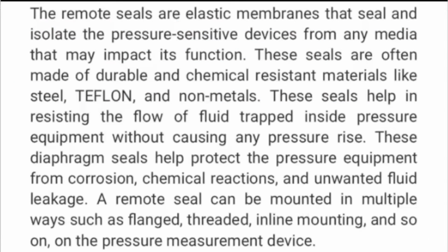Remote seals are elastic membranes that seal and isolate the pressure sensitive devices from any media that may impact their function. These seals are often made of durable and chemical resistant materials like steel, Teflon, and non-metals. These seals help in resisting the flow of fluid trapped inside pressure equipment without causing any pressure rise. These diaphragm seals help to protect the pressure equipment from corrosion, chemical reactions, and unwanted fluid leakage.